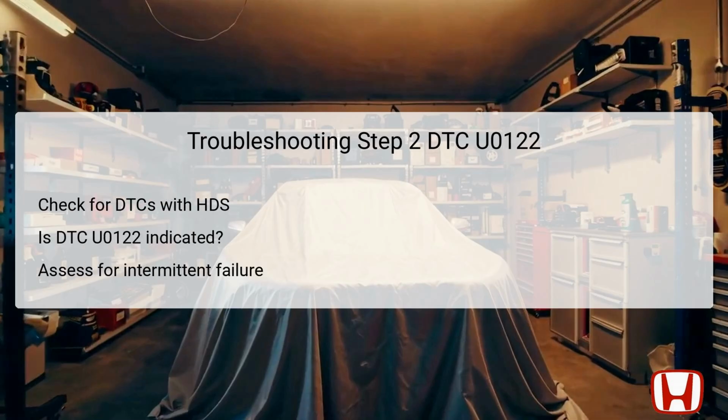In this step, the technician will recheck for any diagnostic trouble codes using the HDS. This process is significant as it helps identify if DTC U0122 remains present after the codes have been cleared.